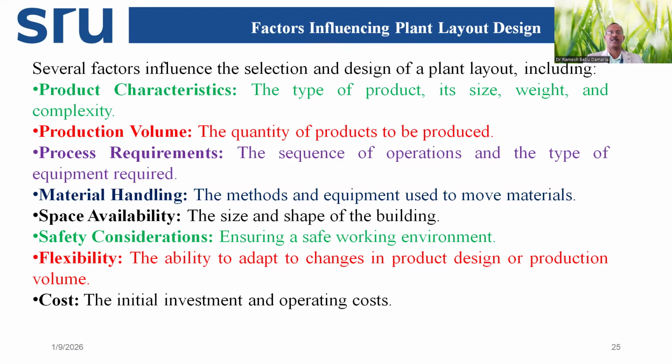If the production quantity is high, more than 1 million, and the varieties to be made are one or two, product layout is the best layout, which allows for mass production. When we want to make, say, more than 2 varieties, 5, 10, 20 varieties of like shoes, laptops, mobile phones, and the quantities are in the order of few thousands, okay? 1,000, 10,000, 20,000, 90,000.